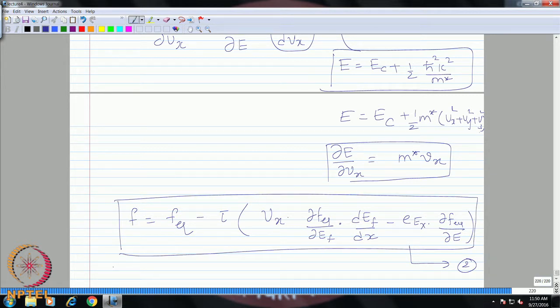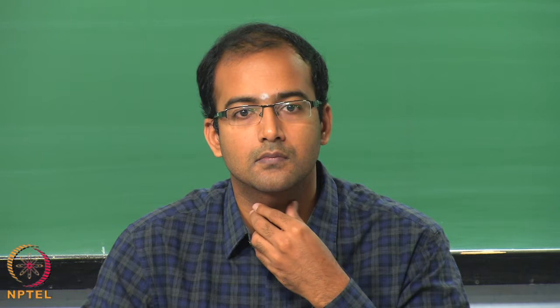Yes. So, is the Fermi level particular for a quantum number, its value is fixed? For that Fermi level, dF equilibrium by dx is dF equilibrium by dEf. That will be fixed if you consider only equilibrium. If you have non-equilibrium, you are looking at different states. Now, you are having different values of Fermi energy along x, then only there can be a gradient to transport the electrons. So, you understand?